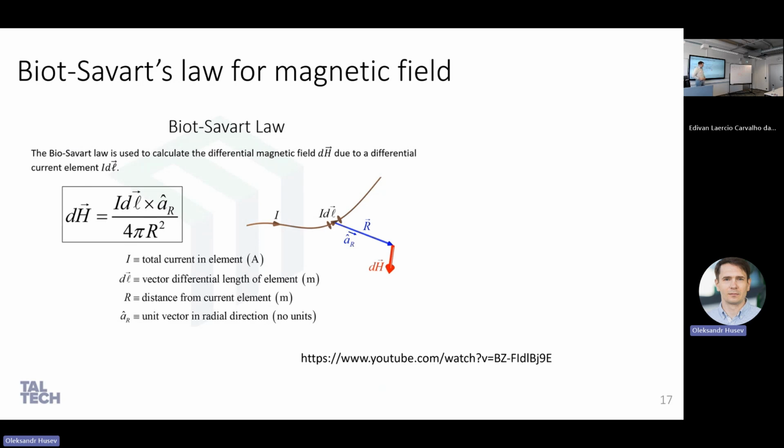Superposition, right? So if we apply it here, and we have current in this direction, and obviously the current comes back, right? In this case, the direction of the magnetic field around is something like this, and the magnetic field created by the return current compensates each other. So definitely the total magnetic flux is much lower.